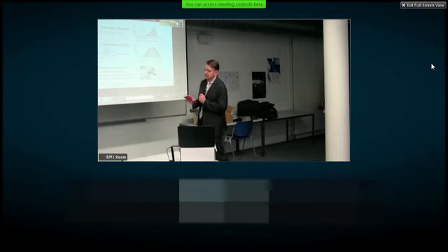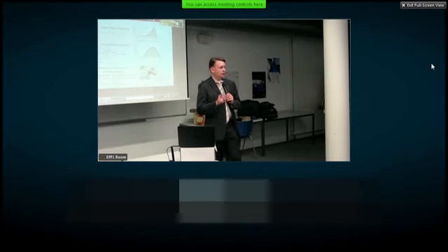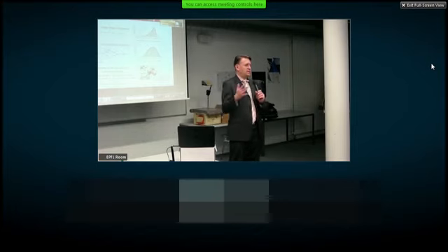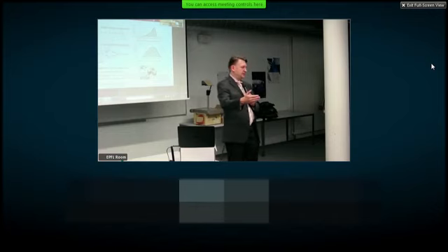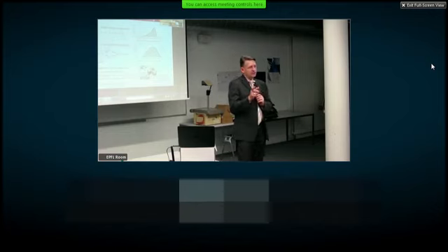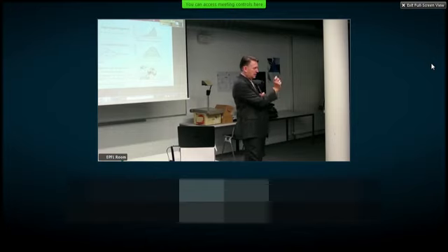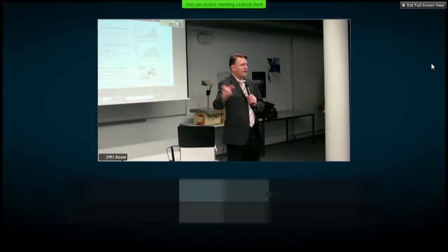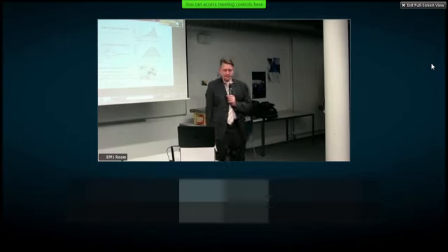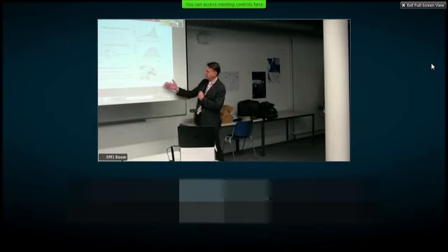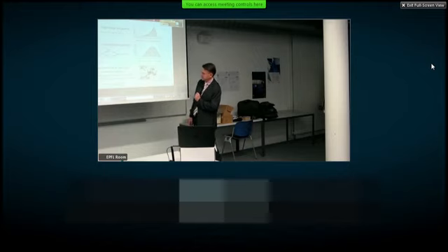So what they looked at was, does it matter whether you do a single stage integration, everything at once, or you do what's called incremental integration? The idea of incremental integration is you just integrate two components or subsystems in isolation at a time. You check them, and then you gradually integrate as opposed to doing it all at once. The example in the paper is a UAV, unmanned aerial vehicle, and there's not a lot of detail, but there are 4 major subsystems: the engine, the flight control system, the optronic payload, and then the payload control system.